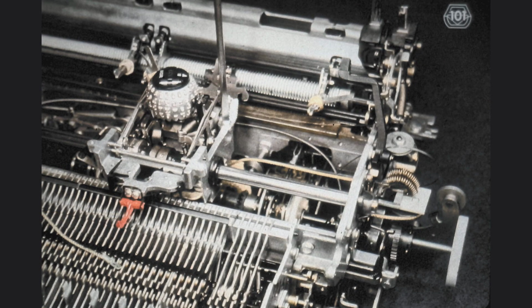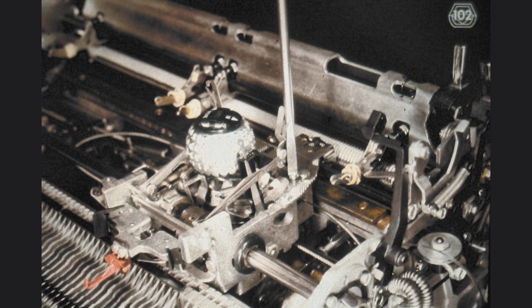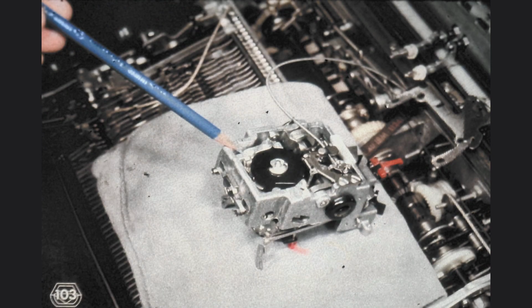Now let us remove the escapement bracket entirely from the carrier. Also remove the print shaft. If you have not yet extracted the tape anchoring screw, do it now. And while you are at it, remove the tilt tape from the tilt pulley sector once again so that we can lift the carrier out of the machine. Once all this has been done, we can remove the carrier from the machine.